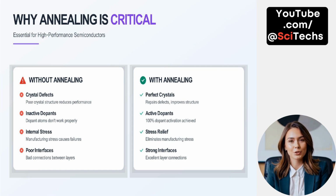Why annealing is critical? Annealing is essential for ensuring the performance and reliability of high-performance semiconductor devices. Without annealing, several issues can arise. Crystal defects may remain in the silicon lattice, reducing electronic performance and reliability. Inactive dopants, introduced during ion implantation, may not become electrically active, leading to malfunctioning devices. Internal stresses from prior manufacturing steps can cause structural weaknesses or even device failure. Additionally, poor interfaces between layers can compromise electrical connectivity and device efficiency.